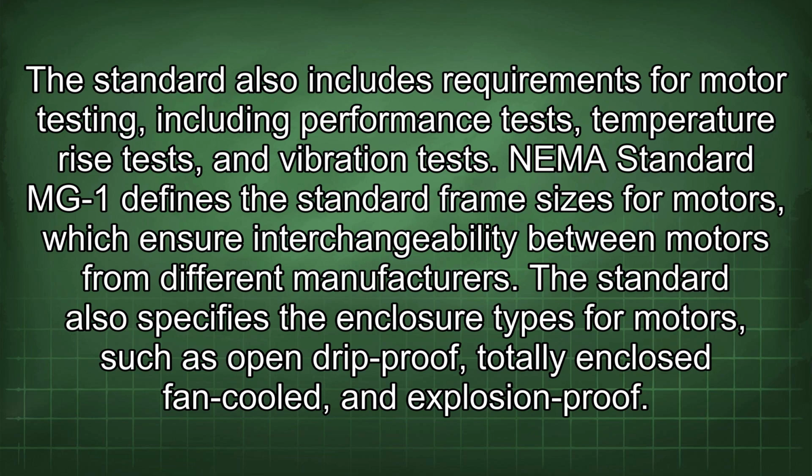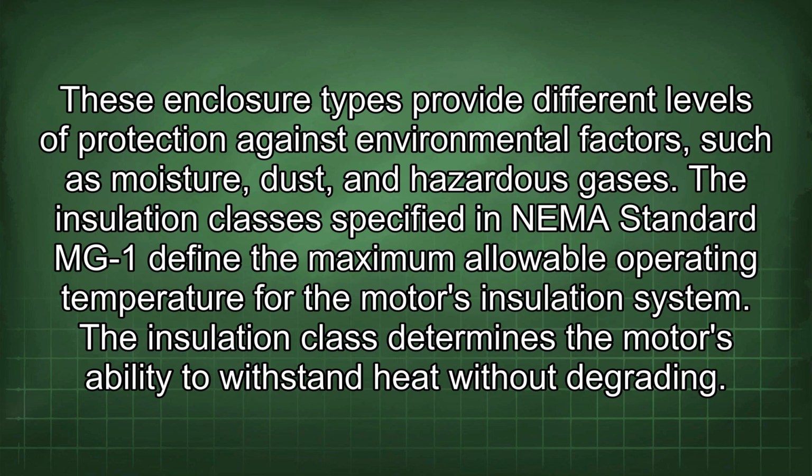NEMA Standard MG-1 defines the standard frame sizes for motors, which ensure interchangeability between motors from different manufacturers. The standard also specifies the enclosure types for motors, such as open drip proof, totally enclosed fan-cooled, and explosion proof. These enclosure types provide different levels of protection against environmental factors such as moisture, dust, and hazardous gases.